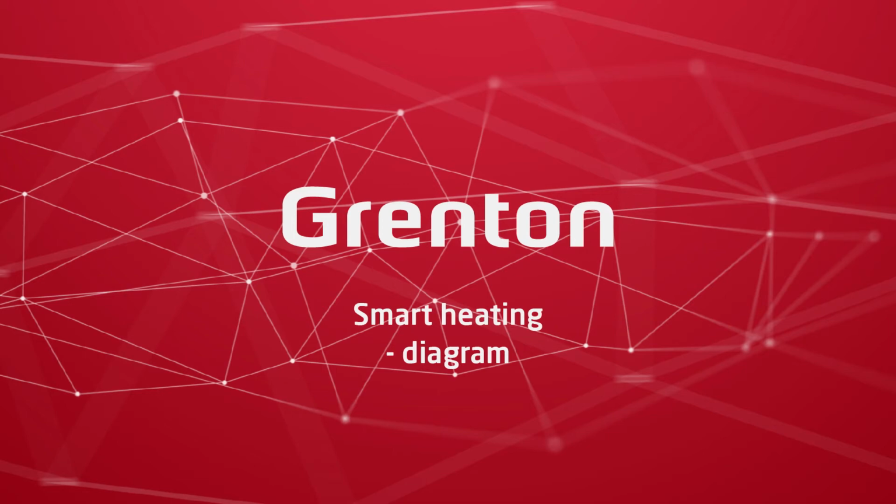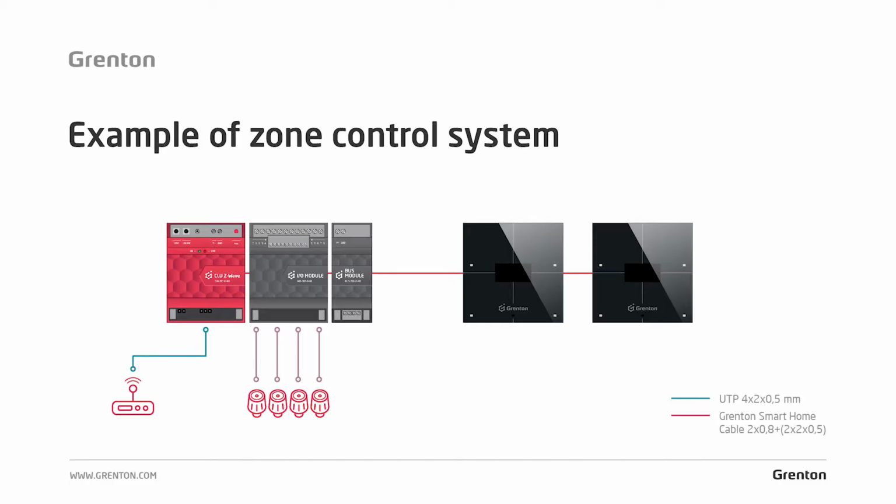We start building the system from the CLU module. At the very beginning there is a CLU module that will store the configuration, and after connecting it to a Wi-Fi router will allow you remote access from your mobile applications. Then you connect the I/O module out of the bus of this module, to which the heating actuators will be directly connected, and next to the bus via the bus module you will connect control panels mounted in each zone separately.